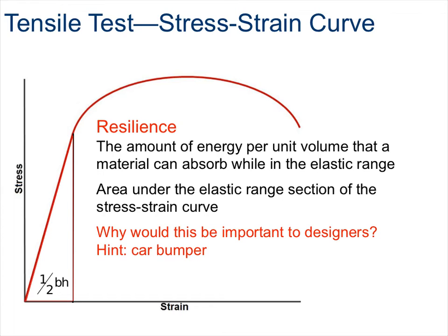In lieu of an engineering stress-strain diagram, a material's elastic quality is represented by a value known as the modulus of resilience. This represents the area under the material's engineering stress-strain curve between the origin and the yield point. The modulus of resilience, represented by the capital letter U, is defined as the measure of the amount of strain energy per unit volume that a material will absorb without experiencing permanent deformation. The value of the modulus of resilience is usually expressed in terms of PSI.